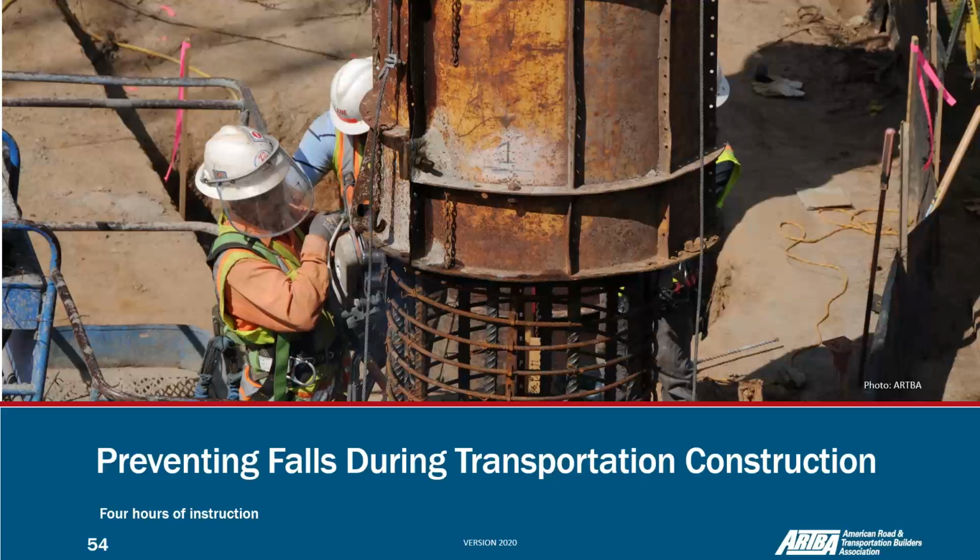In fall protection, we need to create several plans because we have several situations. We reviewed the standards yesterday, and we realized that when we are working above any water, like rivers or lakes in which our workers could fall, we need to provide special protection for them, having a boat with personnel ready to rescue anybody who falls in the water.